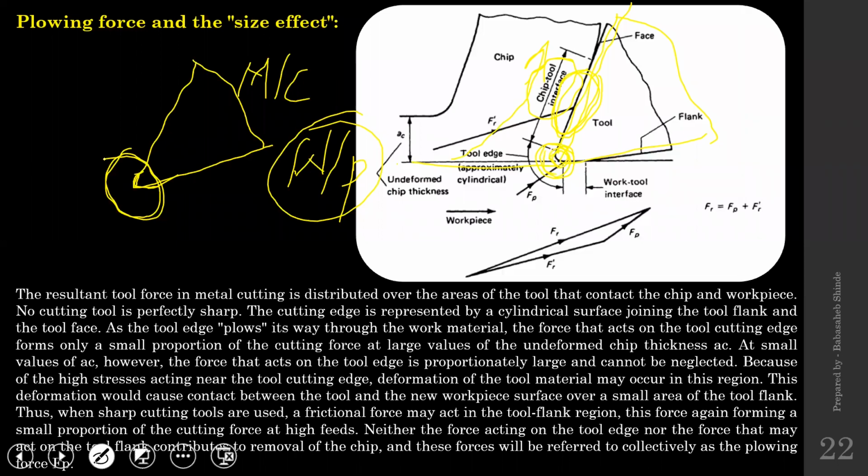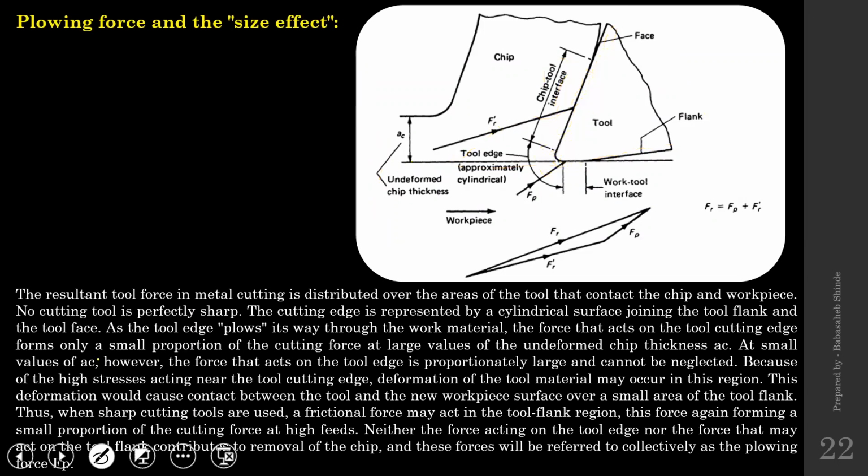In most cases, after machining for a certain duration, this will wear out slightly, and because of that, the surface of the cutting tool will start rubbing with the finished work surface. That is not expected, but it happens all the time. There will be a certain portion of the cutting tool that will be in contact with the finished work surface. So that is the third zone.